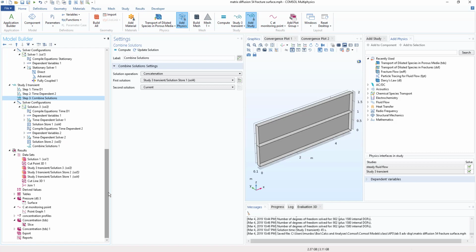Okay, so that's how to set this model up, where we use the fracture as a surface. The advantage of doing this is that we can avoid having to mesh a thin layer. In the previous example, we showed how to mesh it with a swept mesh. That can be fairly efficient, but nevertheless, for some examples we might have many fractures, and we simply wouldn't want to mesh their thickness. It would add elements unnecessarily, perhaps, and complicate the problem.